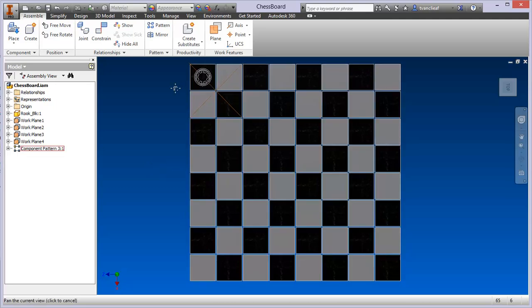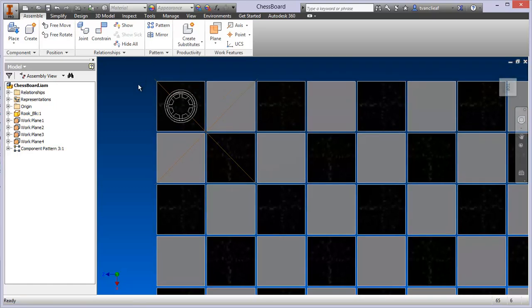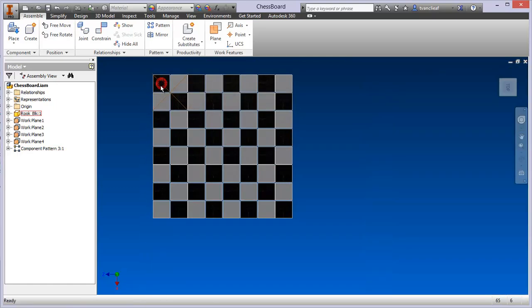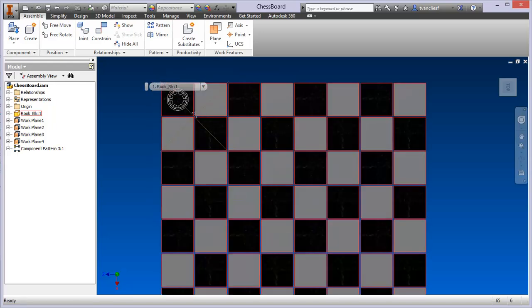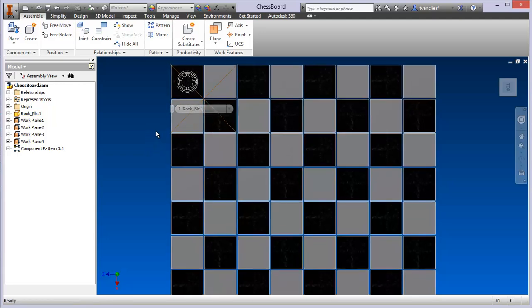Another thing that you can do at this point too is make patterns for the pieces, so you know that these are going to be essentially the same thing. You could come back in after and use the replace to make the new parts. I've only got the rook in place at this point, but that's not to say that you can't start placing these and then modifying and resaving the part as, say, bishop or knight, that sort of thing. So that's essentially what we're going to end up doing here, but we'll say that that's good enough for the patterns video.